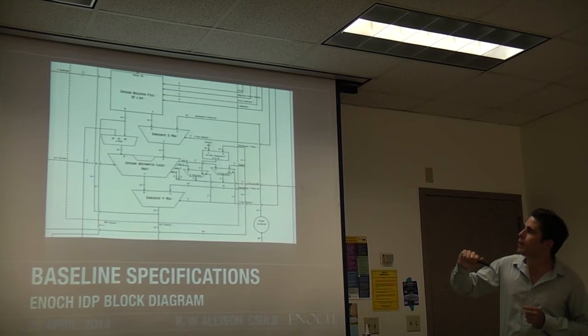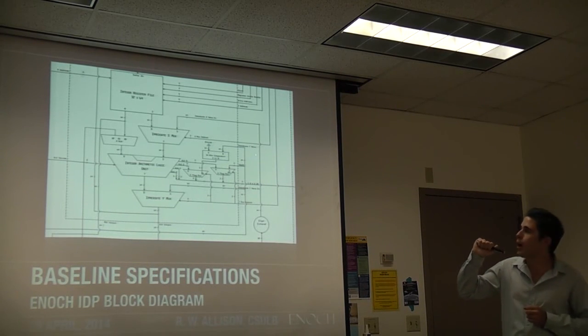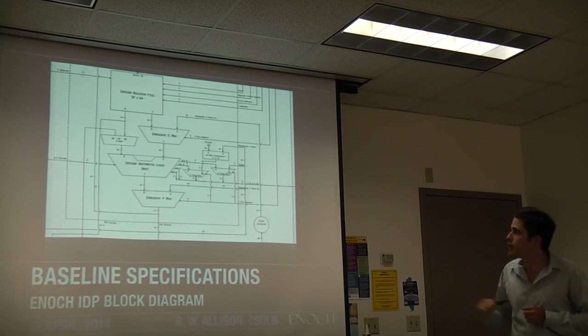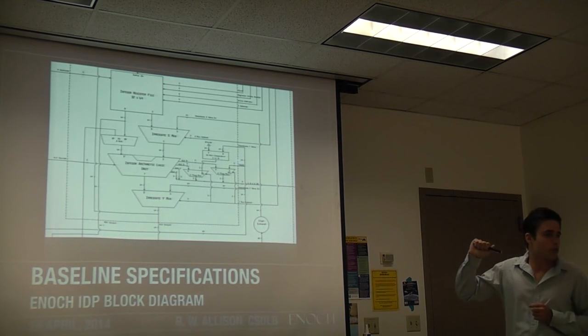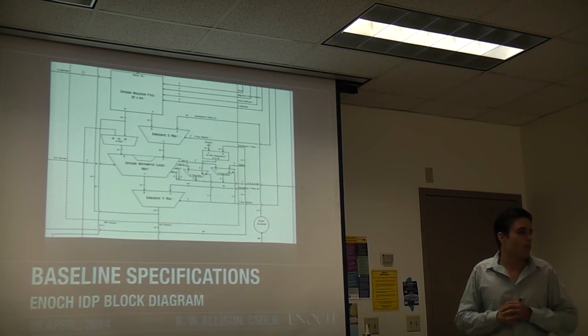And this 64-bit comparator here is tied to ground, 64 bits of ground, along with our entire 64-bit immediate Y value that we use for loading immediate values. It's a comparator to ground, and if they are equal, it inputs 0 into here. That way we can check immediate values being put in, whether or not there's 0.